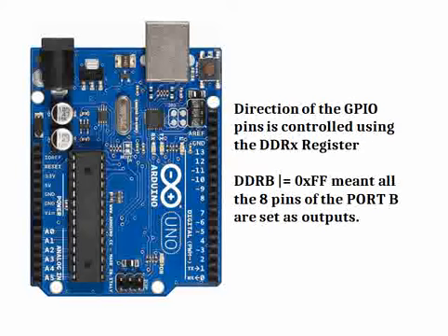To drive that, we said first we have to set the direction to output instead of input and then drive it. To set the direction of a particular pin, there is a register called the DDR register. X represents the port. We have 3 ports, we already discussed that. The pins of a particular port can be driven using this DDRx register.